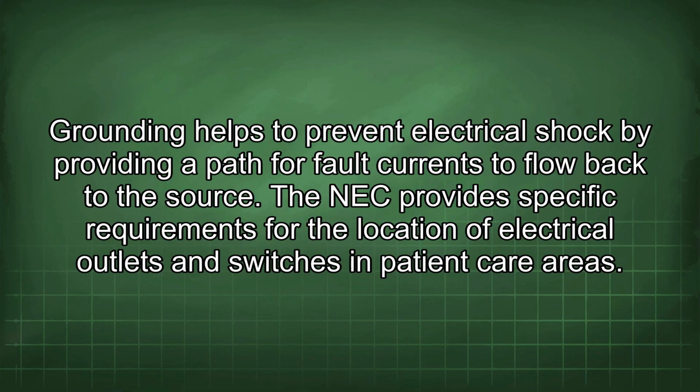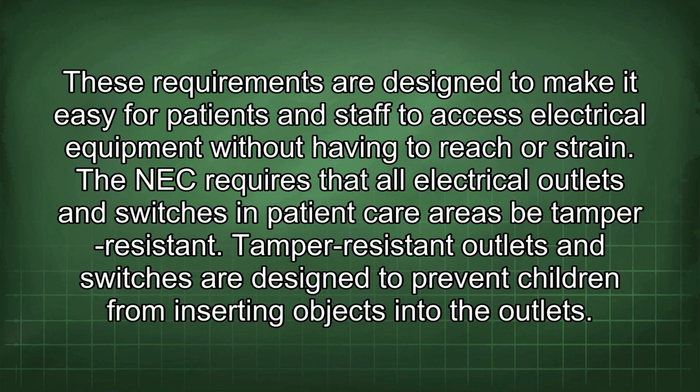The NEC provides specific requirements for the location of electrical outlets and switches in patient care areas. These requirements are designed to make it easy for patients and staff to access electrical equipment without having to reach or strain. The NEC requires that all electrical outlets and switches in patient care areas be tamper-resistant. Tamper-resistant outlets and switches are designed to prevent children from inserting objects into the outlets.